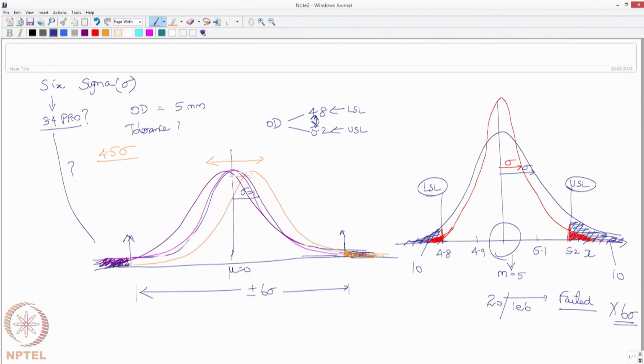So, this is a deterministic factor of safety for a probabilistic concept. The factor of safety that is used is 1.5. That is why it is actually not 6 sigma, it is 4.5 sigma. Now, do not go outside and say this 6 sigma is actually not 6 sigma, but it is 4.5 sigma. Not the majority of people appreciate this concept. This is the math behind it.